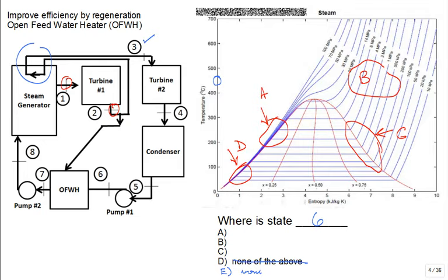All right, let's see. Maybe this will get a lot. Oh, that's pretty good. Isn't it A? Yeah, it's A. Now, why is it A? Okay, think about this. We're about ready to go into the pump. If you're about ready to go into a pump, what is the best state of the fluid going into the pump? Saturated liquid. If it's condensed liquid, that's okay, but it's not maximally efficient. So saturated liquid is what we like to bring into the pump.